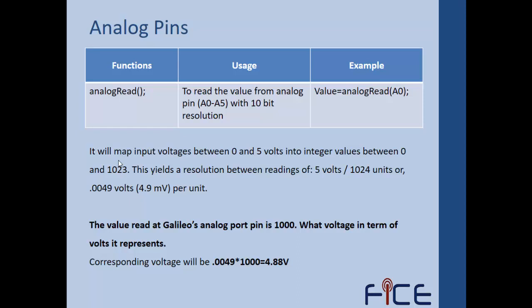So basically analog pins are nothing but the inputs of the ADC. This Intel Galileo Gen 2 board has an onboard ADC. So this is nothing but the input of the ADC. Obviously we cannot write something and we cannot have output from the ADC input pins. That is another reason. So analogRead is the API.